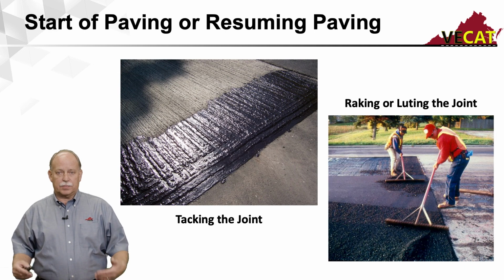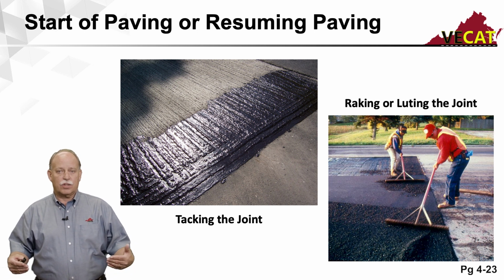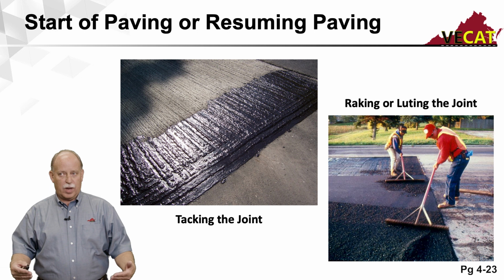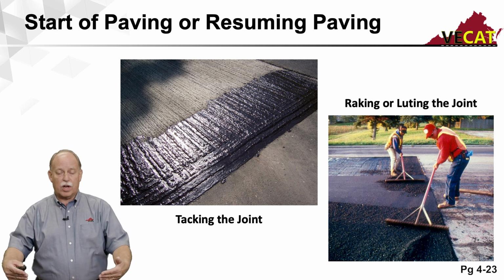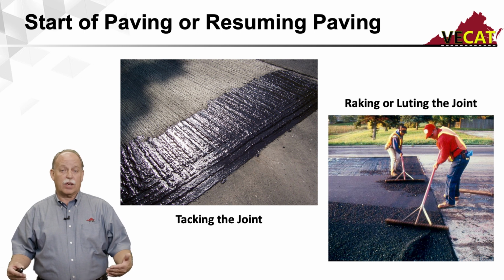Talked about tacking. Tacking is absolutely critical. You have to tack that transverse joint. So at the start of paving, or when you resume your paving operations on another day, you've got to make sure that you tack that joint, you tack it well. That transverse joint, if it's not tacked correctly, then it becomes a conduit for water to get into those cracks, and therefore it'll fall apart.